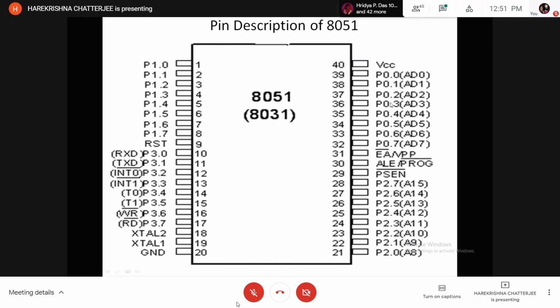But see here, the port 0 pins can be used for 3 different purposes. On the same pins we can connect an input device or output device directly, say the 8 data pins of an ADC, or 8 switches. Or these pins can be used as the external address bus to carry the low order address of the 16-bit address bus, A0 to A7.